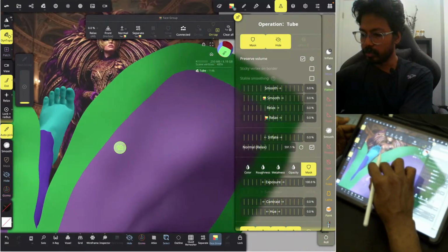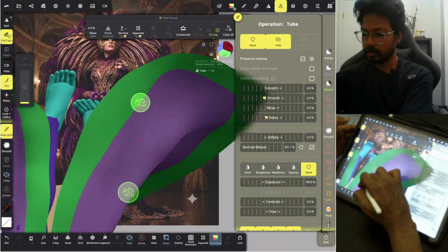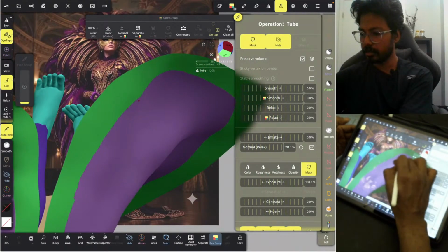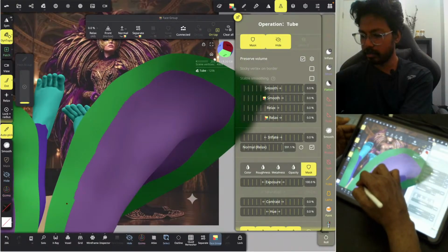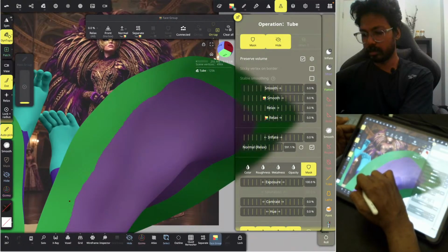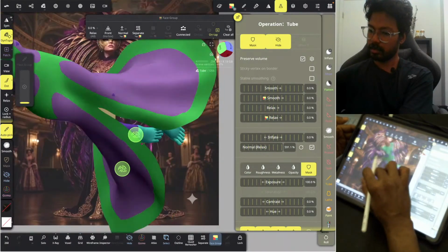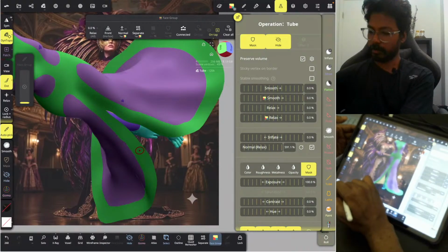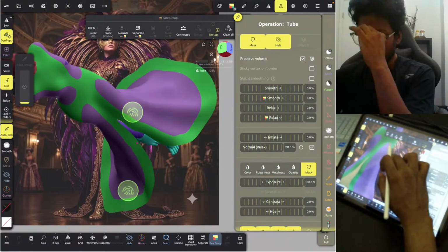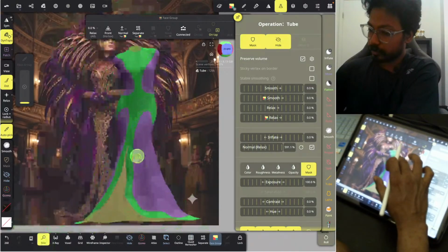Yeah, don't worry about those sharp edges which we are getting. Can solve it by remeshing. While remeshing, it automatically relaxes those coarser edges, and voila, we got it. Let's save it before anything weird happens.